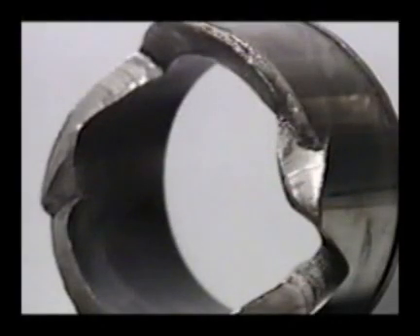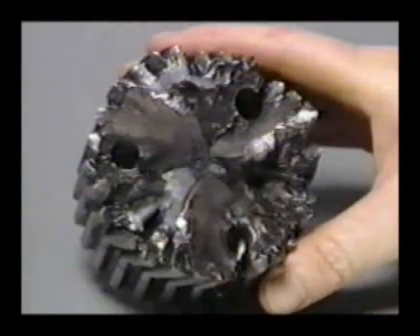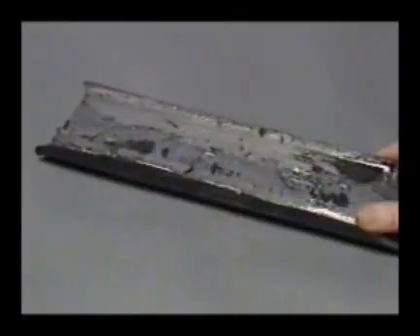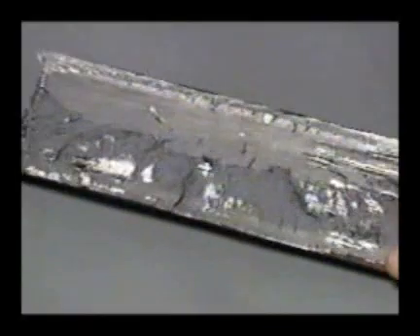Torsional fatigue cracks often leave distinct beach marks and progress at 45-degree angles within a part. Reverse torsional fatigue can produce a starburst fracture like this, or an X-shaped crack. The fracture first grows in one direction and then the other as the load reverses direction. Fatigue fractures produced by longitudinal shear loads usually grow along the grain flow, leaving a somewhat woody appearance.